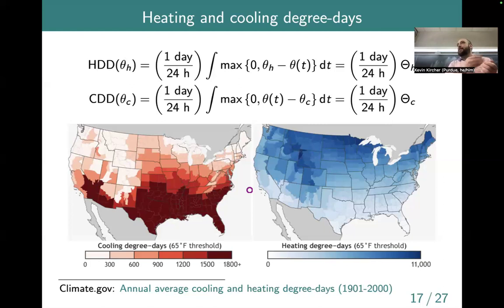If you had a data set, like a spreadsheet with the date and the average outdoor temperature for that day, you would take that average and subtract it from 65, the balanced temperature. Suppose today's average temperature was 35 Fahrenheit. We would take 65, subtract 35, that would give us 30. We multiply it by 1 day, and that would be 30 heating degree days from today.